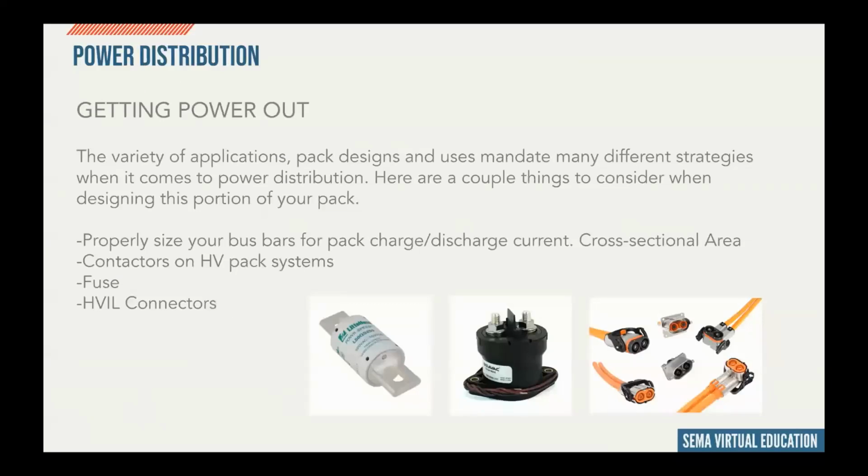Power distribution, to dig a little bit deeper on what power distribution is: the ability to get the power, the energy stored inside, out of the pack, outside the enclosure, and doing it in a very safe way. Because of the variety of applications, pack designs, and uses, there are many different strategies available to do this properly.